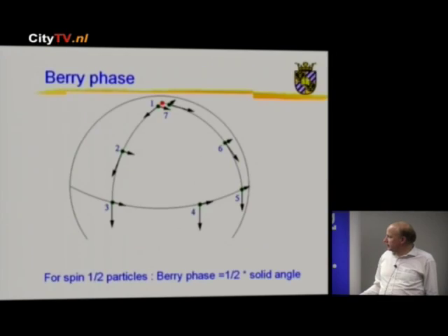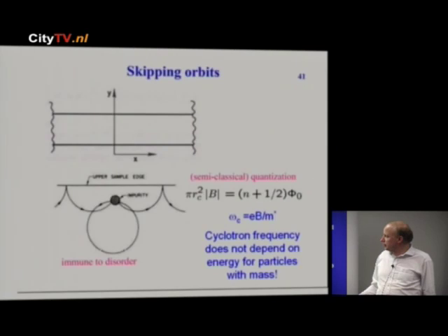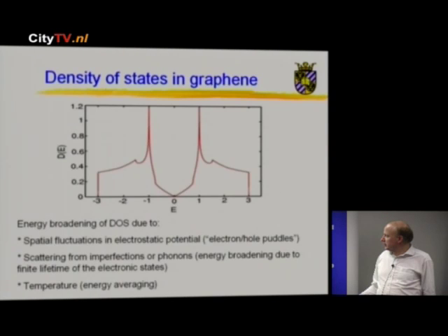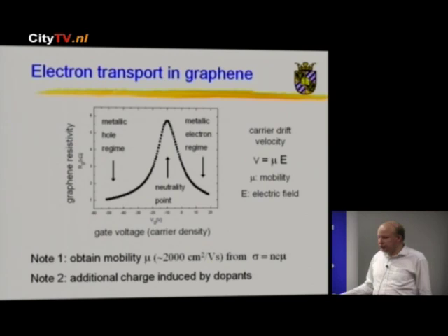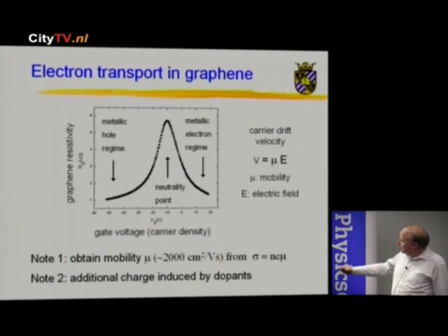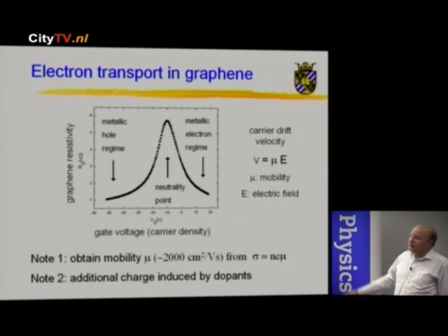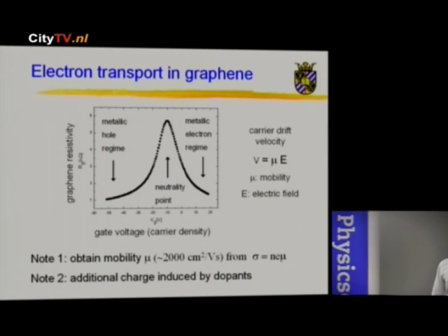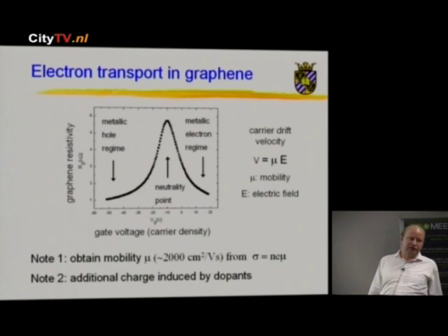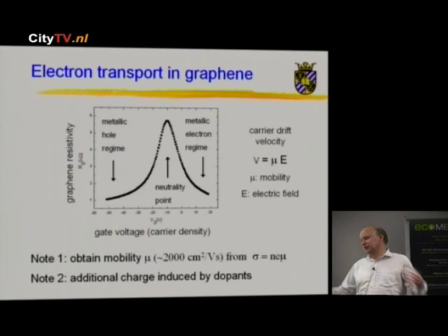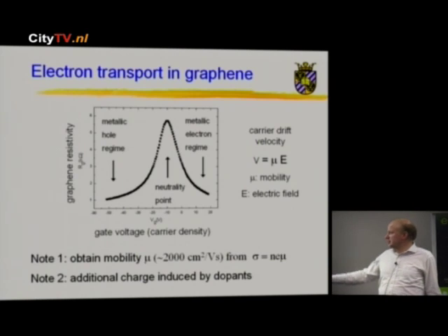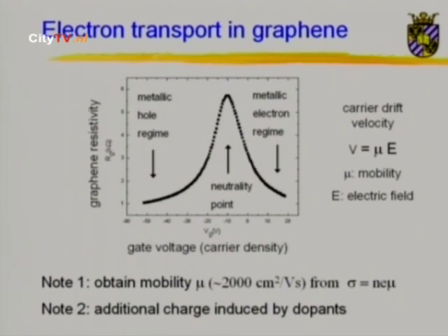You already see these effects. For instance, if you measure this curve at room temperature, in atmosphere, you do not get a nice curve. What you get is hysteresis. Basically, if you go this way, you get a peak here. If you go this way, you get a peak there. Why? There is charge on your graphene, which can come and go. So this is always measured in vacuum, but it shows the sensitivity of your graphene to whatever is on it.